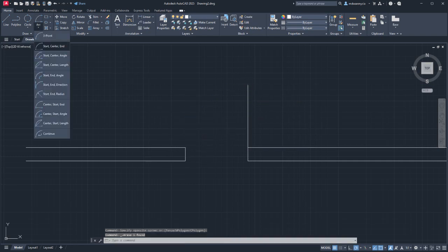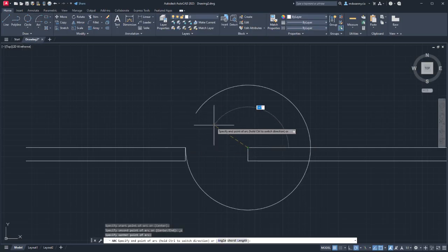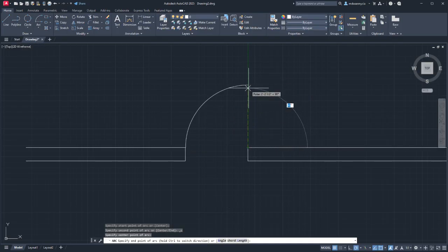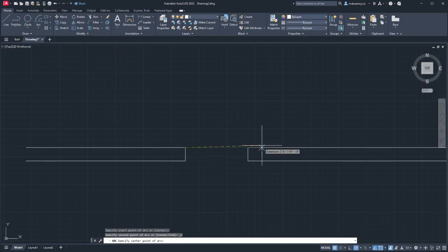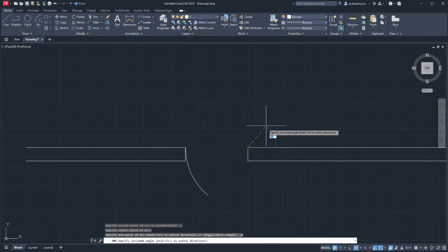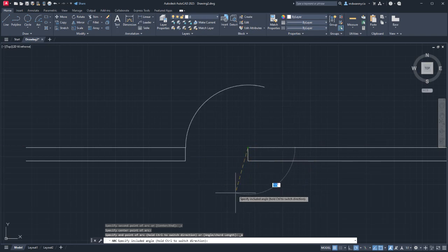Depending on what information you have available, for example, maybe I don't know that point is there. Maybe I just have my start and my center, and I don't know what the point is that's up here. Well, now I can draw this because I can just snap it to that angle. Whereas if I know start, center, and angle, it's going to be a bit more of a pain because now I have to go 90 degrees.